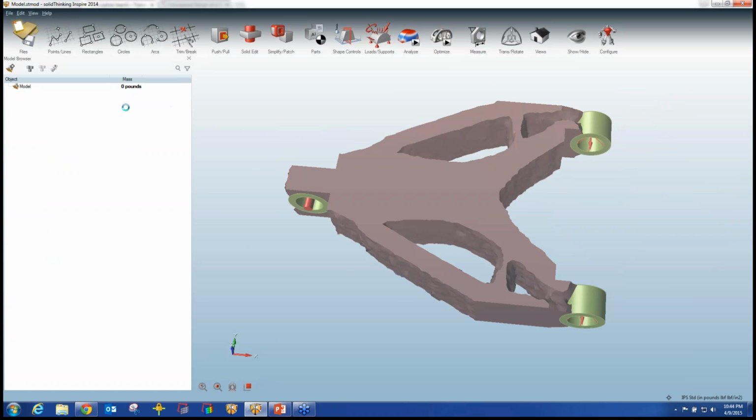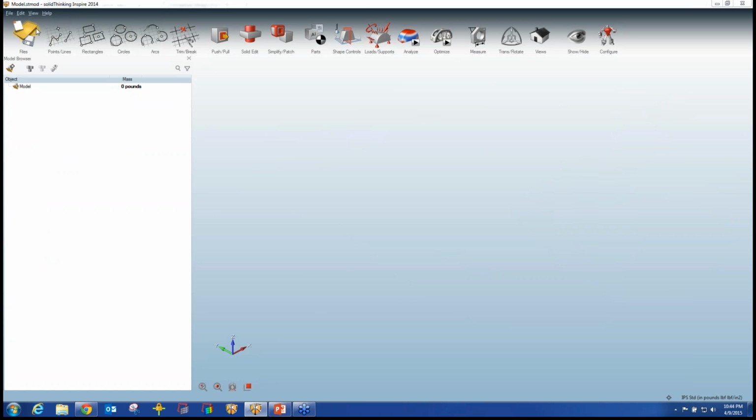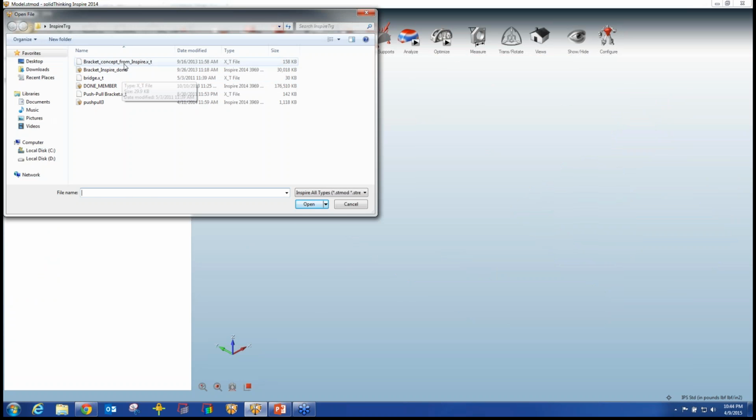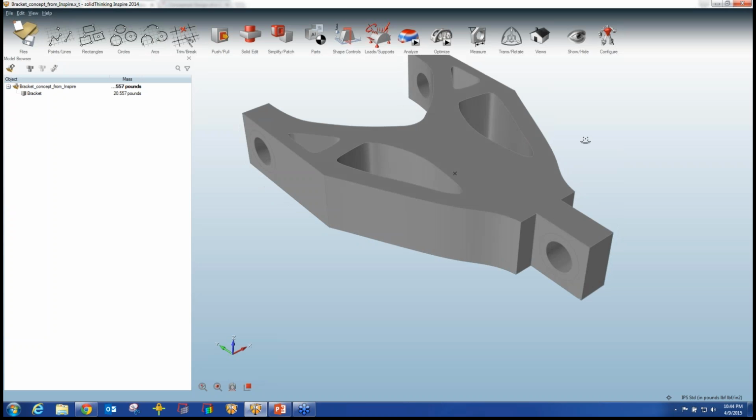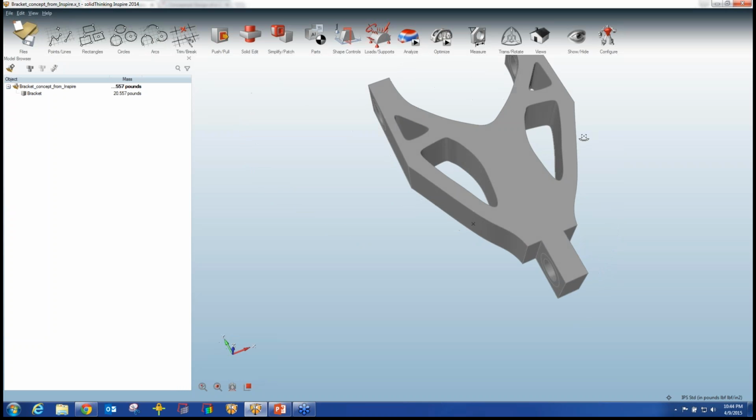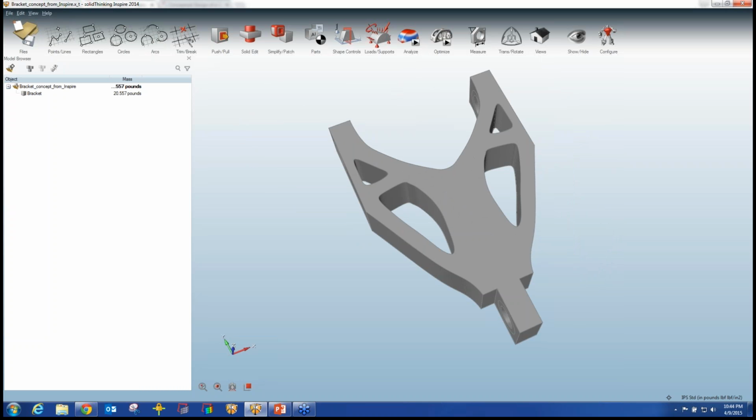There isn't any smoothing algorithm that's going to do that, except a human being with a clear idea of what he wants. I wouldn't directly just smooth it and use it, because in any design, right now I'm just removing mass and making it stiffer, but then I also have to take other design considerations like aerodynamics. I need to put in holes for lubrication, and there isn't a smoothing software that can do that. So I am going to smooth it myself.